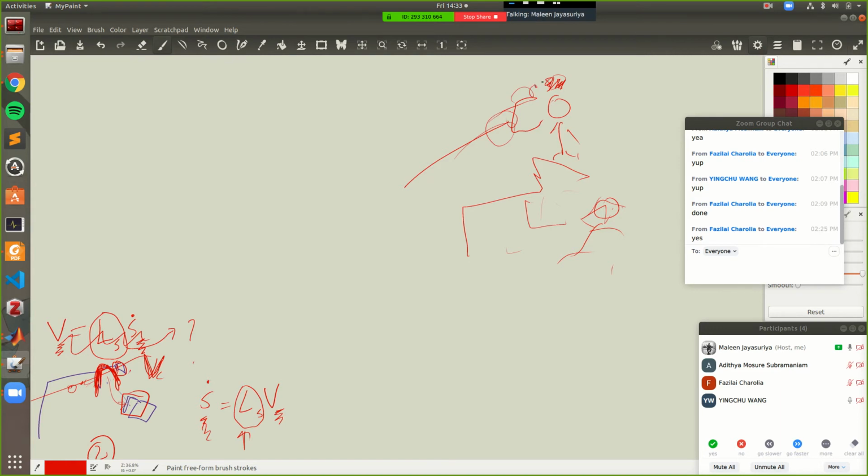But what you're doing now is first detecting the person, determining their 3D location, and then telling the robot to go there. That assumes that the initial detection is 100% correct, that you detected the exact location of the person, and you are telling the gripper to go there without any feedback.